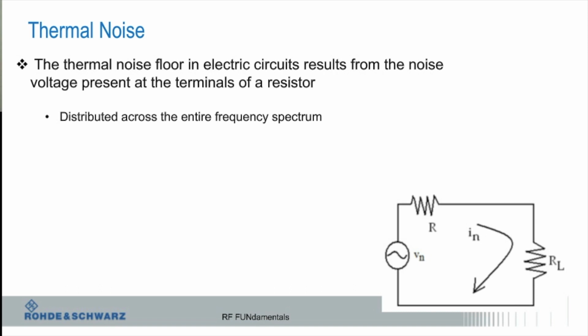Amplitude noise is that signal going up and down a little bit. But thermal noise really has nothing to do with your circuitry. It's just the real-world environment that we're in. So forget about spurs or interferers or things like that, but just the real world has this broadband noise spectrum, which is what we typically call KTB. And the standard number people use is minus 174 dBm per hertz at standard temperature. And we'll get into that in a little bit.